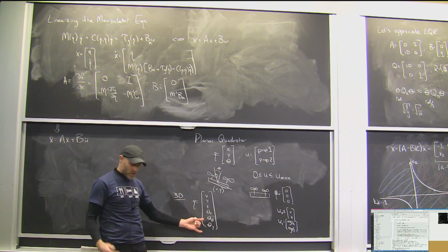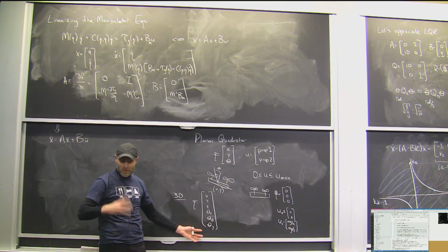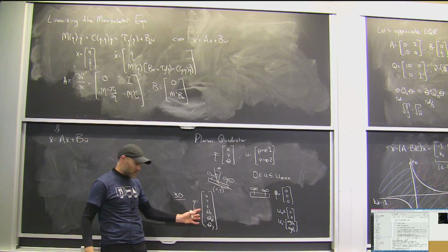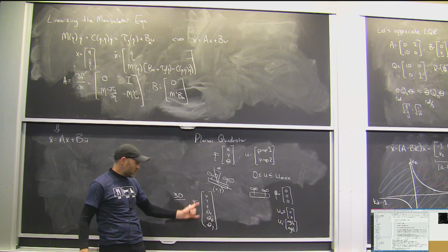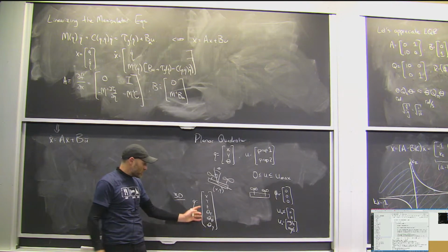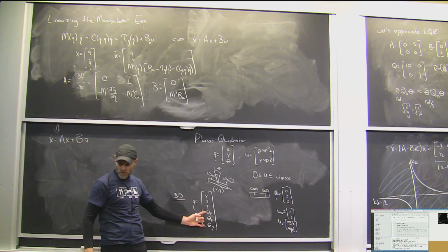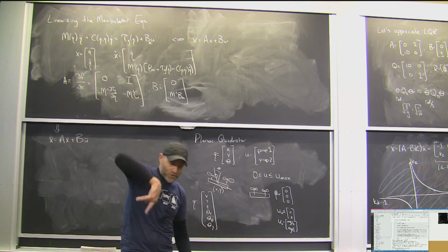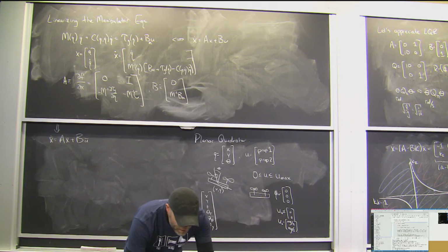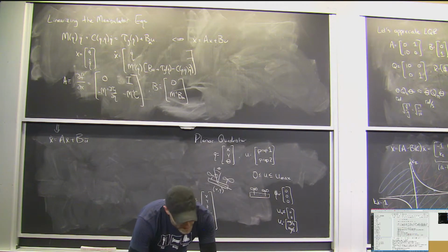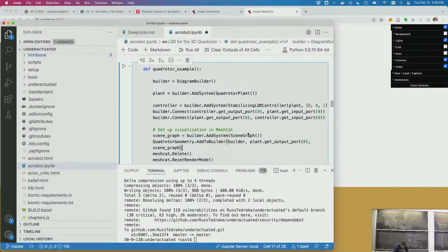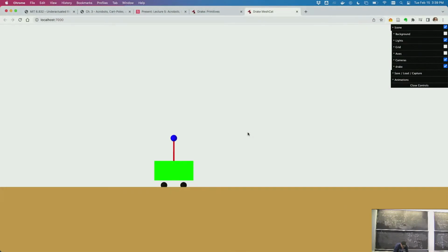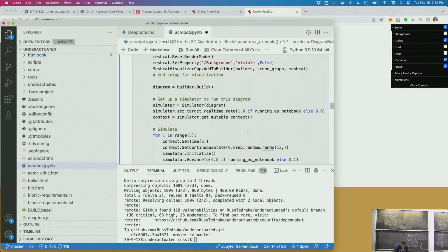That parameterization has problems. For those of you that know about quaternions and other things like this, you can do the same work with quaternions, but if you want to use the recipe from today so far, just use a yaw pitch roll representation of 3D orientation. As long as your quadrotor is not upside down, it's going to be okay. And if your quadrotor is upside down, I guess you're already getting out the spare propellers or something.